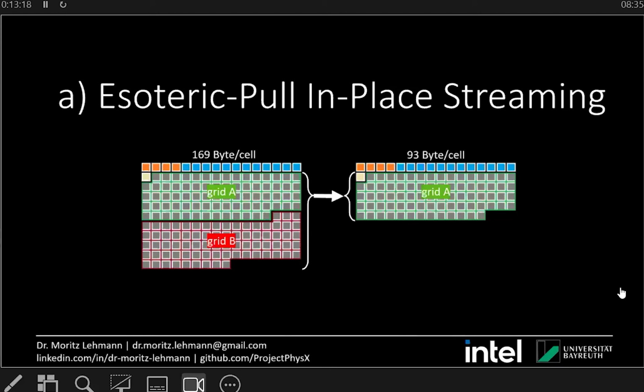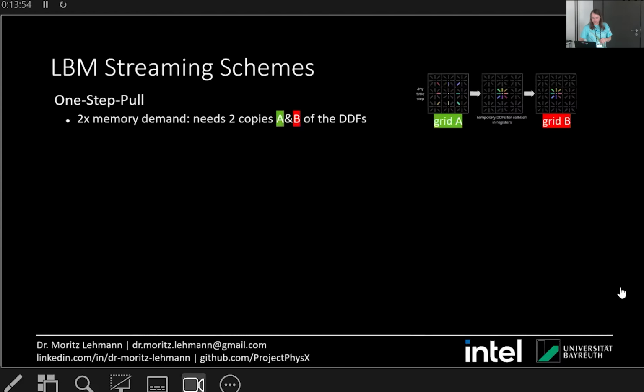The first is realizing that lattice Boltzmann on a GPU traditionally is quite bad because it needs 2 copies of the density distribution functions in memory, 2 redundant copies. It's a bit like implementing the game of life, where you need to read all of the neighbor cells and do the ruling for the center cell and then save the new center cell to solve for the dependencies of neighboring grid cells. And what I did is a solution that gets rid of the redundant copy.